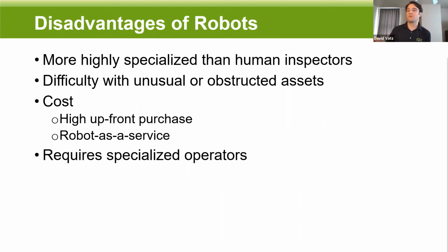Based on the result, we were able to save the mill about $20,000 on the tank floor repair, because instead of repairing the entire floor, we identified an area of serious concern that needed repair, and the rest of it was actually in okay shape. This would be really hard to find with manual inspection because you wouldn't be able to collect enough data to really understand.